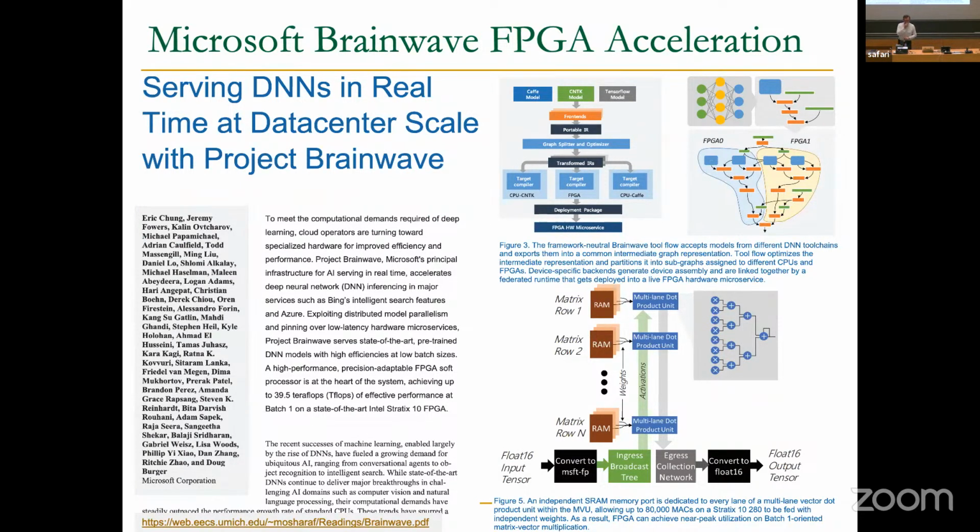Okay, I should also say that people have been using FPGAs for this. Microsoft has developed what they call the Brainwave system. Essentially, they use FPGAs as a substrate to accelerate machine learning operations. And they do multiple things. Partly, they do some specialized data flow mapping, as you can probably see somewhere over here. I mean, you need to read the paper, but the paper doesn't give a lot of detail. But they do partly data flow mapping, directly accelerating part of the data computation. But they also put soft SIMD units on the FPGA, just like you're doing in your labs right now. You're putting a soft processor, a MIPS processor, on the FPGA, right? You're not accelerating an application. You're basically implementing a processor on the FPGA substrate. They actually have a SIMD processor on the FPGA substrate also.